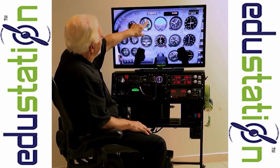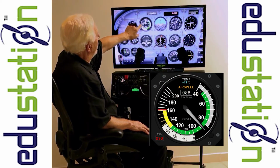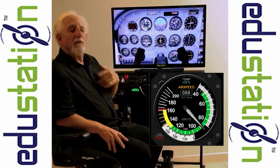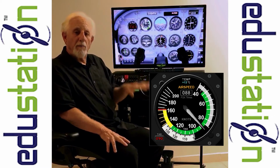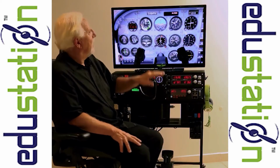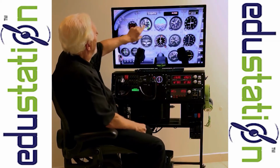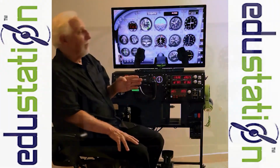So you'll notice in the airspeed indicator there's a green area, a yellow, and a red. The green area is where we've induced enough lift to overcome the weight and gravity holding this airplane on the ground. We're going to rotate, gently take off at about 60 knots or greater.